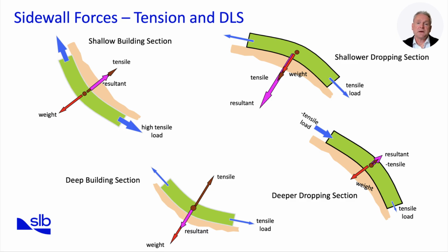The sideways component is dominated by tension, not weight. Note the high tensile load indicated by the large blue arrows. The high side force into the top of the hole can result in key seating. The rule of thumb is to keep these doglegs low.